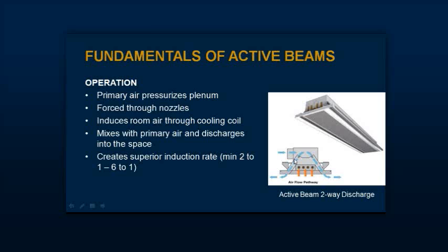Now, water, of course, requires a ventilation system. So we typically see displacement ventilation used a great deal, or overhead mixing for that matter. Active beams being a water system that actually is a mixing system at the same time on the air side, and sometimes natural ventilation. So I'm going to go into more detail on the displacement, the mixing systems, and the beams, and I'm going to sidestep the natural ventilation due to lack of time.